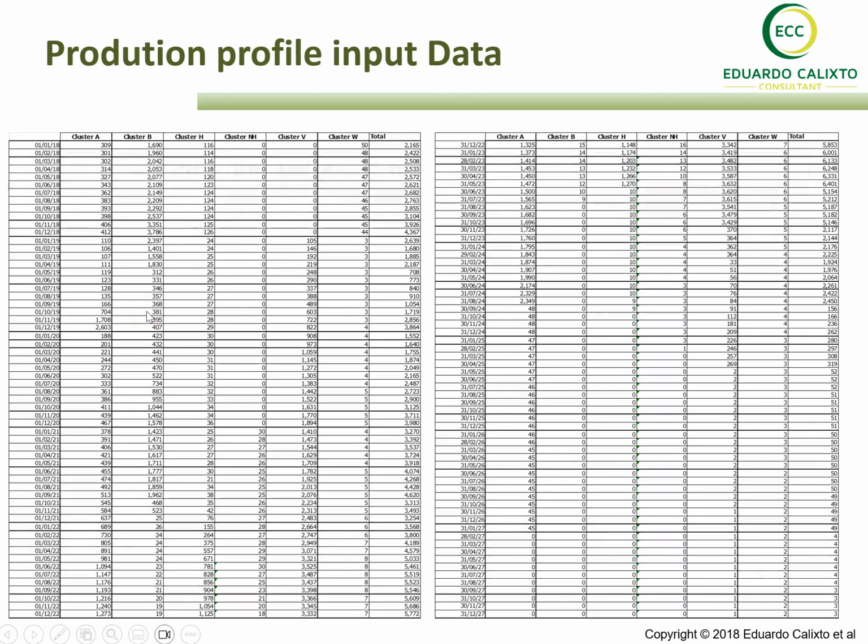So we have all this information for all equipment that are under the scope of the analysis, and with these inputs we can decide to build the RBD. Because in the specific case of a gas platform, we are modeling and predicting the production, we need to know the production profile. And here is one example, we have 1, 2, 3, 4, 5, 6 wells, and these wells produce a specific gas, and in the end we have the total production that goes to the gas platform. And we need to consider this profile as the production gas profile.